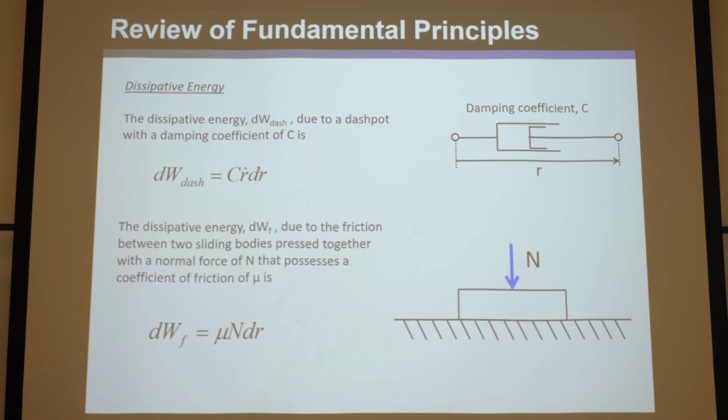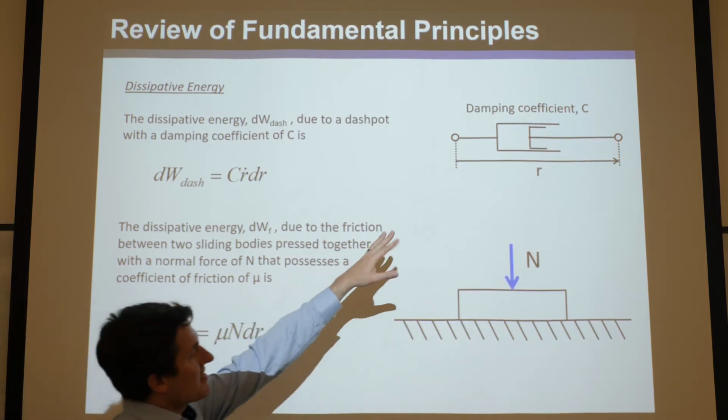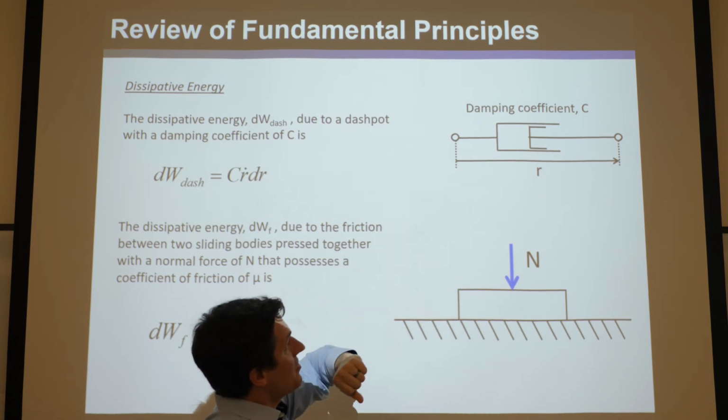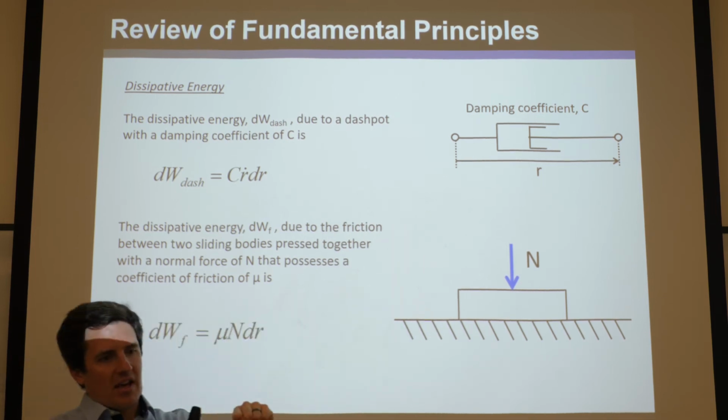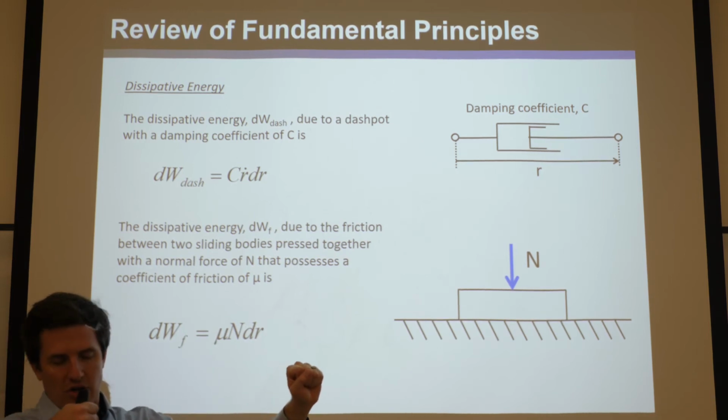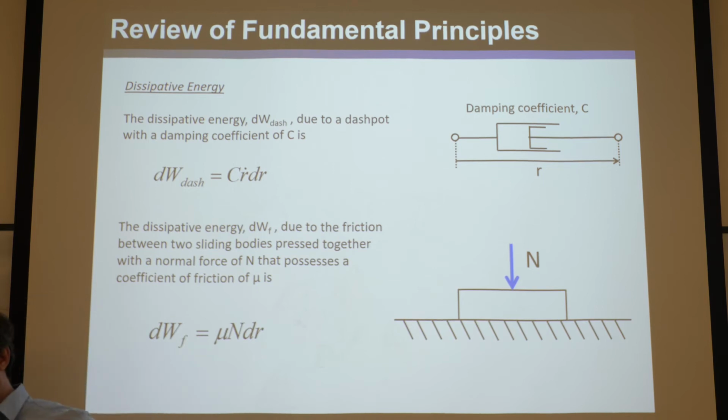So when you have a dashpot, say a syringe or something that's filled with honey, here's a schematic on the right-hand side, and you have the distance between the two. You can imagine, unlike a spring where the force that it resists is proportional to the displacement, it's actually proportional to the velocity that you're going to pull it, right?